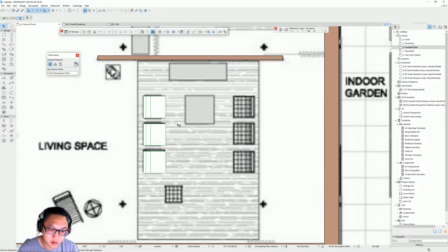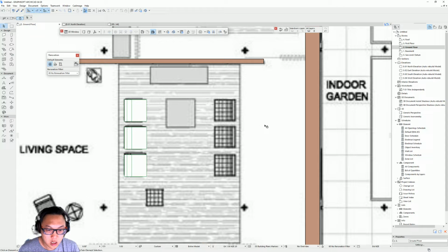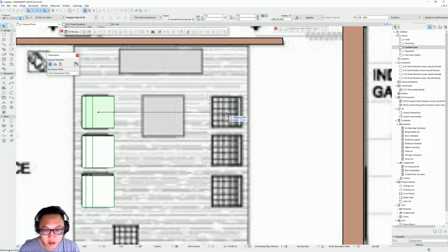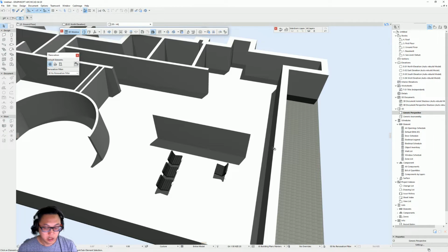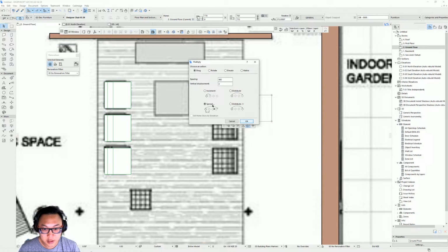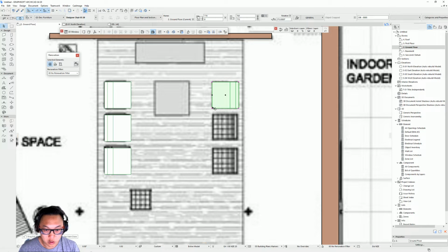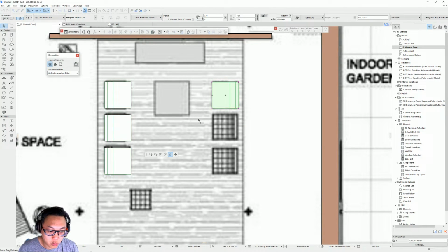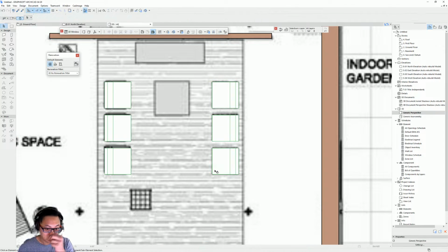And here there's another way of placing furniture. And okay, so now if you want to put it on that side, you can make a copy, drag it along here, 3125, and then you can select the center, rotate it, so now it's facing this way, but it's a bit, and then you can just do the same thing, multiply, and 60, or you could just use the other one, distribute, set 2, and use that point here as a reference. Press shift so you can stick it here as a reference to have the same here. So that's one way of doing it.